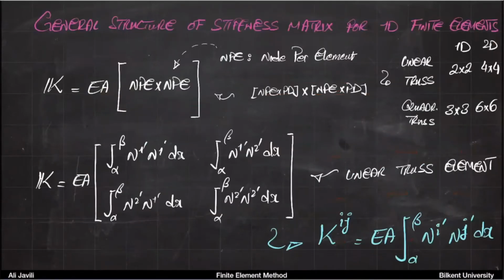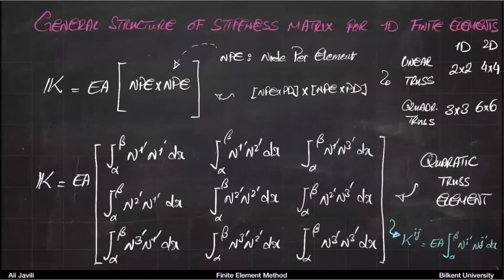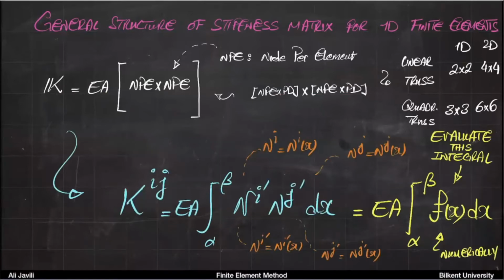And eventually, if you unify everything, you come to this picture. So you will have a stiffness matrix that looks like EA times something, and that Kij can be understood as just one function. And then again, if it is quadratic, of course, this is the same thing, or if it is linear, this is the same thing. But now that we have this, we know that the problem, from that differential equation, we have come to a single stiffness matrix.